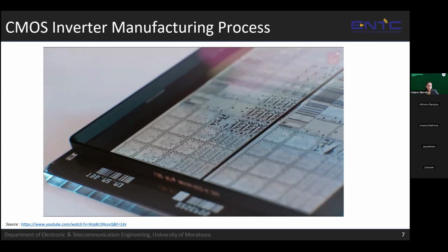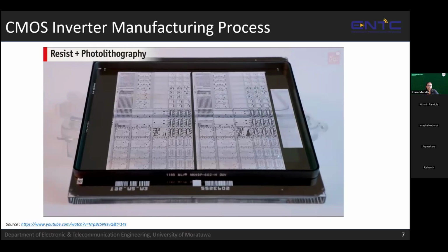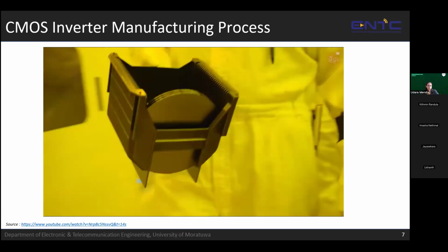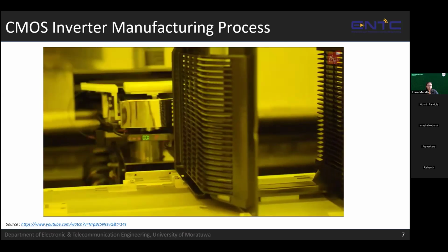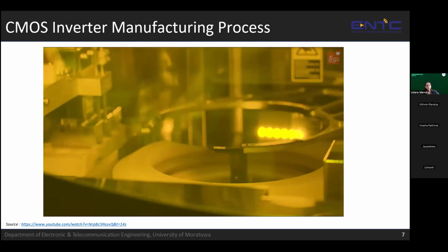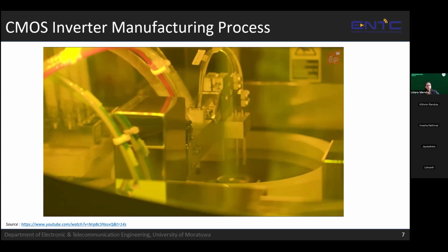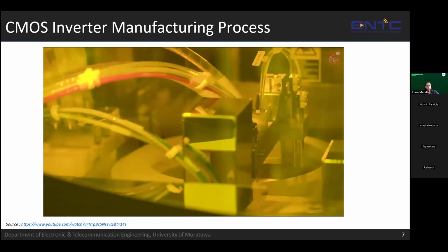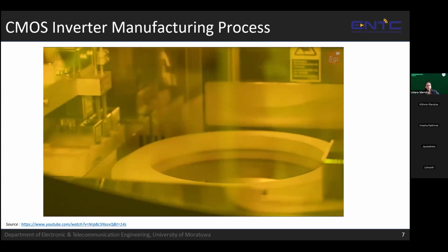To create a pattern, the method of photolithography is used. An optical mask is irradiated with UV light to transfer the geometric design to photosensitive resist. The first step is to spin coat the resist onto a wafer. This coating technique involves placing a small amount of resist on a substrate. The wafer starts to spin, which spreads the liquid resist over the entire surface, creating a uniform film.